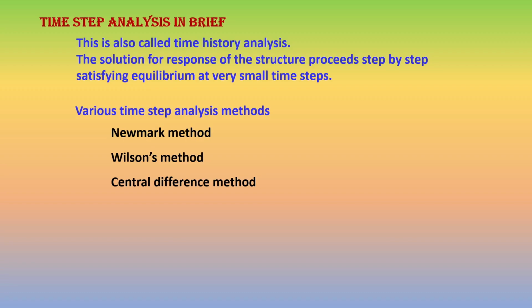The time history analysis goes step by step on the time domain. So you take a very small time step size, maybe 0.005 second, and consider the equilibrium of the system. Applying the equilibrium, you can get a solution of the structure in the current time step.